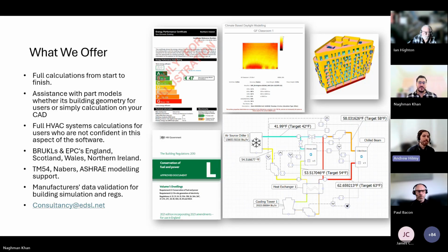And again, you've got the simulation events window. So anything that Systems finds a bit funny when it's simulating, it will make a note of and report in that window. Yeah, and then when you click on one of those warnings, it will zoom you into where that component is and that day and that hour where that event occurs. So you can inspect exactly what's going on with that schematic, with the values in each of the different places.